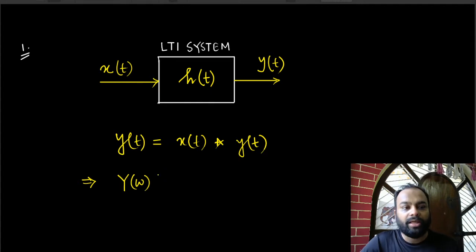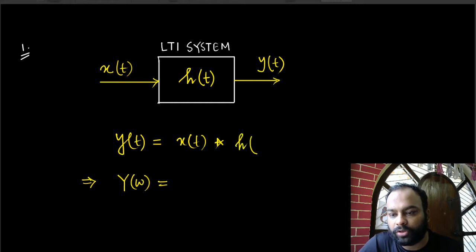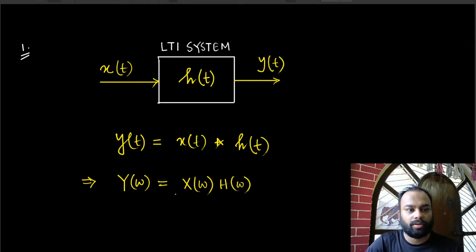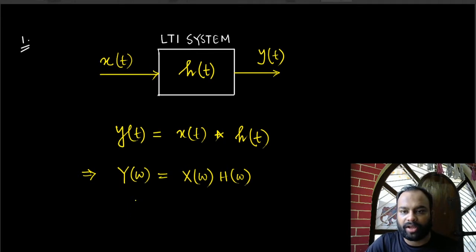Now with the convolution theorem, you can understand that, of course, this is the convolution in time domain. In the frequency domain, after applying the Fourier transform, if the Fourier transform of x(t) is X(omega), the Fourier transform of y(t) is Y(omega), and, of course, I wrote it wrong, and none of you corrected me somehow, and if the Fourier transform of h(t) is H(omega), then using the convolution theorem, we have this. So without any difficulty, that can be understood.